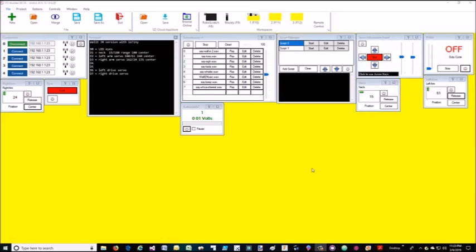I had a couple more ports, but I just wanted to do it. And it's a neat way that you can use multiple switches, touch devices, off of one line rather than multiple lines. If you're using multiple inputs, you can save some lines that way.